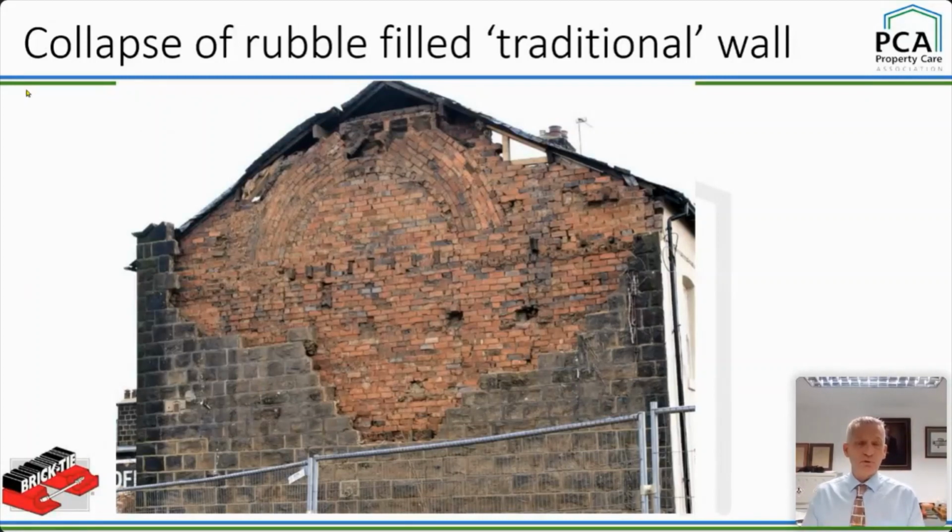But it's an example of, in effect, wall tie failure, but there are no metal ties in there. If you just look at my brand new giant cursor, look at that. That's proper Yorkshire cursor. If we look at that, we can see the chimney flue there. We can see the floor joist that used to bear into the wall. Well, they still do, but they used to stick it in a cavity.